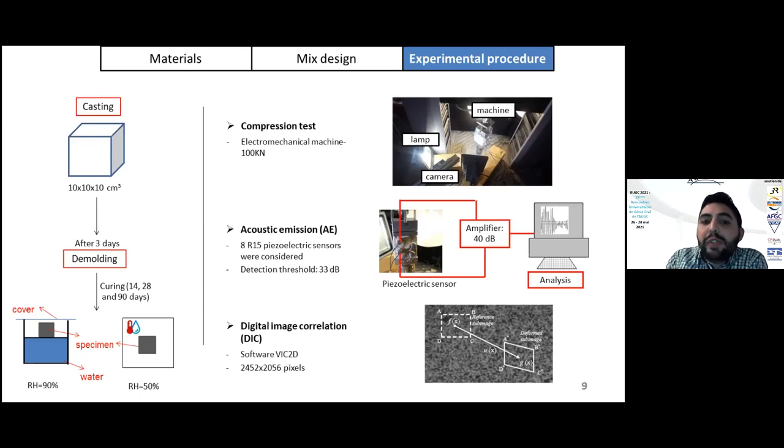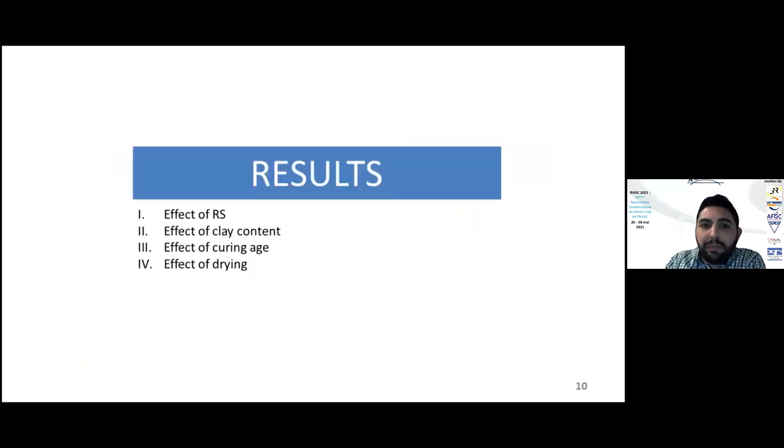In this study, we used 8 piezoelectric sensors, and the detection threshold was kept at 33 decibels to avoid any environmental noise. For the digital image correlation, the software VIC-2D was used.